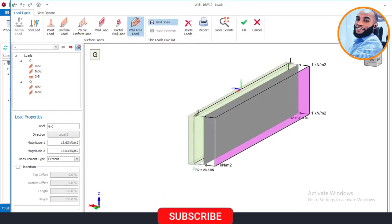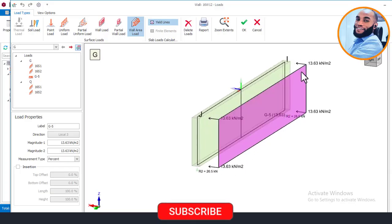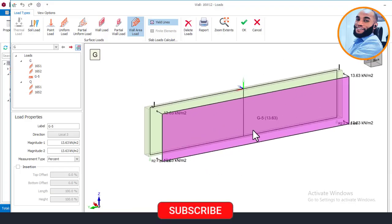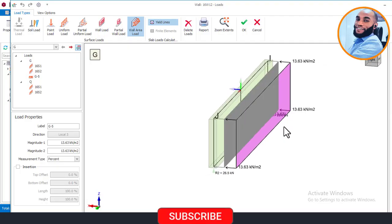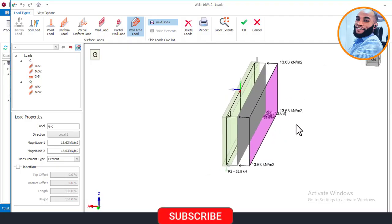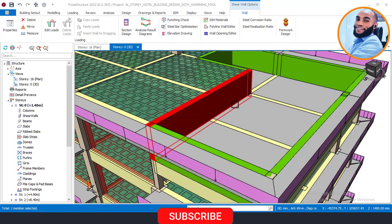Now once I click on this update, you see that all this load data showing 1.0 kN per meter will change to 13.63. So I'll come here and click on update, and you will see them change right now. You can see that all our loads have now changed to 13 point this. What this means is that what is acting on the surface of this wall is a 13.63 kilonewton per meter square load, and it's acting on this retaining wall. Once I do that, I will come here and click on OK.